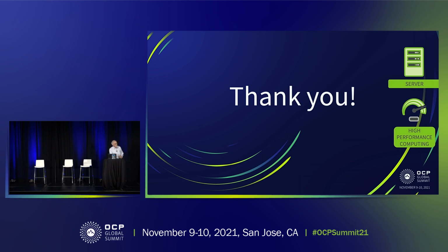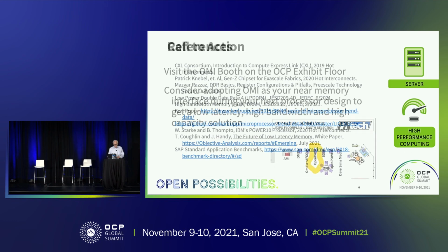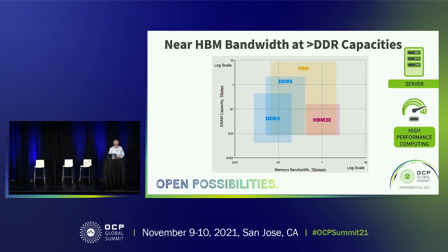Do you have any updates or insight in terms of the throughput that you can get in the DIMM with DDR5? I think you're still a little bit bandwidth limited with DDR4 on the OMI DIMM. You're talking about for the DIMM, yeah. In the OMI interface, you have 28 gig SerDes going there. I was just wondering if you had any insight on when we're going to hit the bandwidth capability with DDR5 on a module to take advantage of the speed.